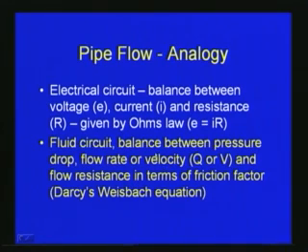So, we can have a one-to-one correspondence with the electrical circuit, for example, Ohm's law. In a very similar way, in the fluid circuit, we can compare the pressure drop with the voltage, the flow or velocity with the current, and the resistance in an electrical circuit with the flow resistance in terms of the friction factor, and the Darcy-Weisbach equation which we have seen earlier, with the corresponding electrical circuit system.